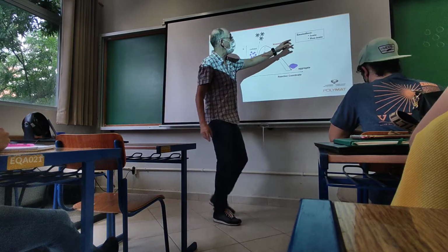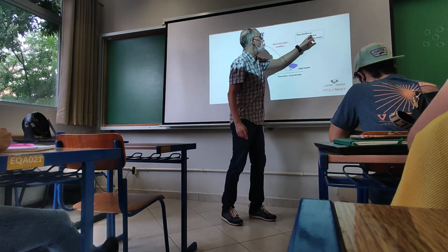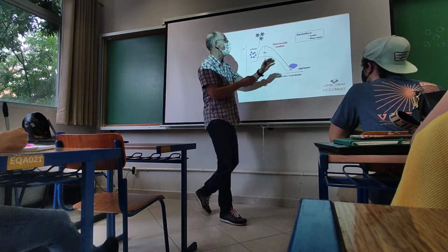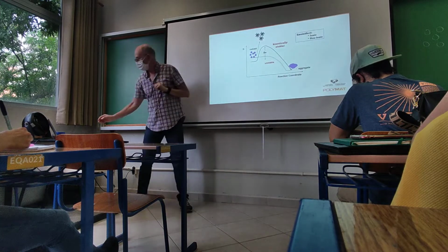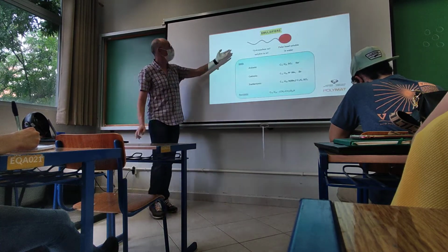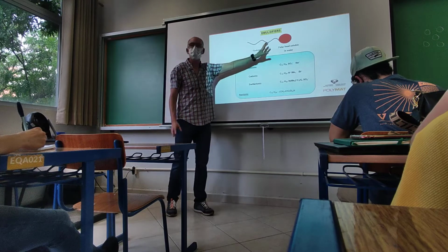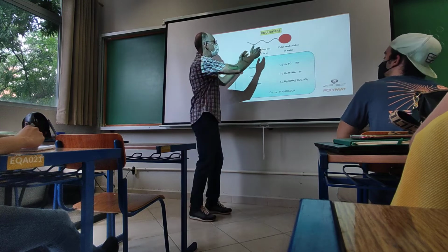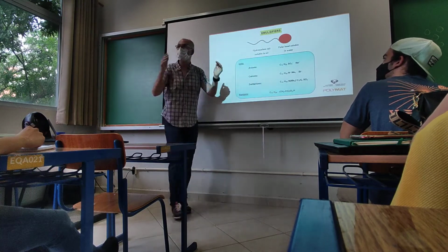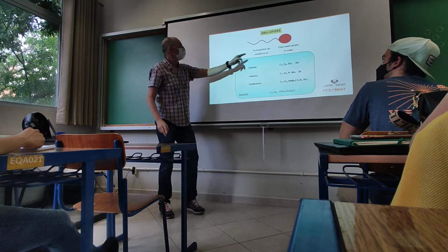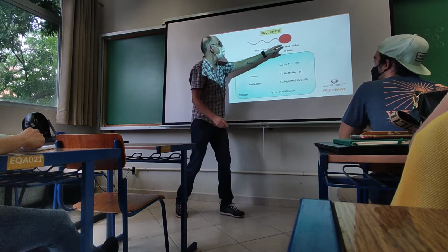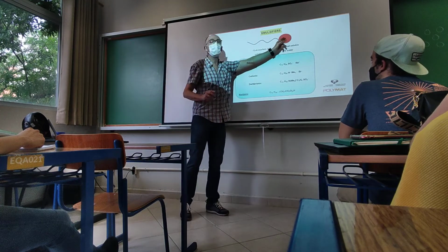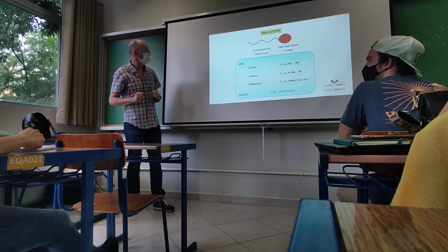And for that, we can use emulsifiers, which can be ionic, that they have charge, normally anionic surfactants, or non-ionic surfactants. Okay? So the surfactants or emulsifiers are amphiphilic molecules. An amphiphile basically is a molecule that contains a tail, a hydrocarbon tail, which is hydrophobic, non-soluble in water, but soluble in oil, and a head, which is hydrophilic, okay, which is soluble or happy in water.